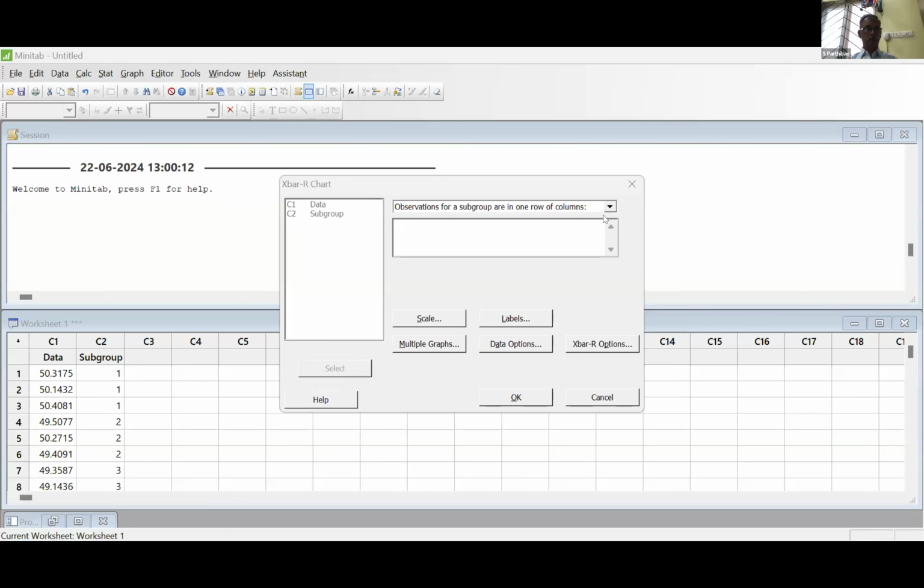Yeah, one more additional question. Sir, if the process is statistically stable only, we will be calculating CP and CPK. That is also correct. If the process is stable, then in that case your CP will be healthier. See, your CP will be healthier if your process is stable and if variations are less, right?